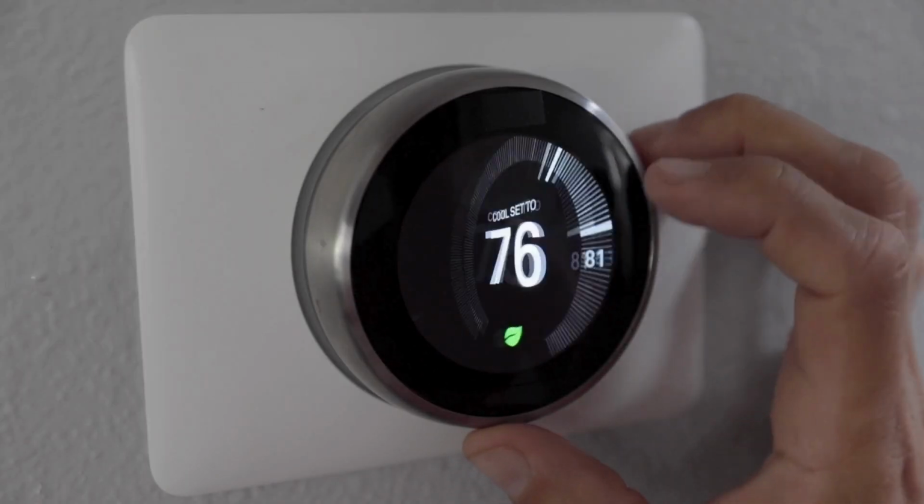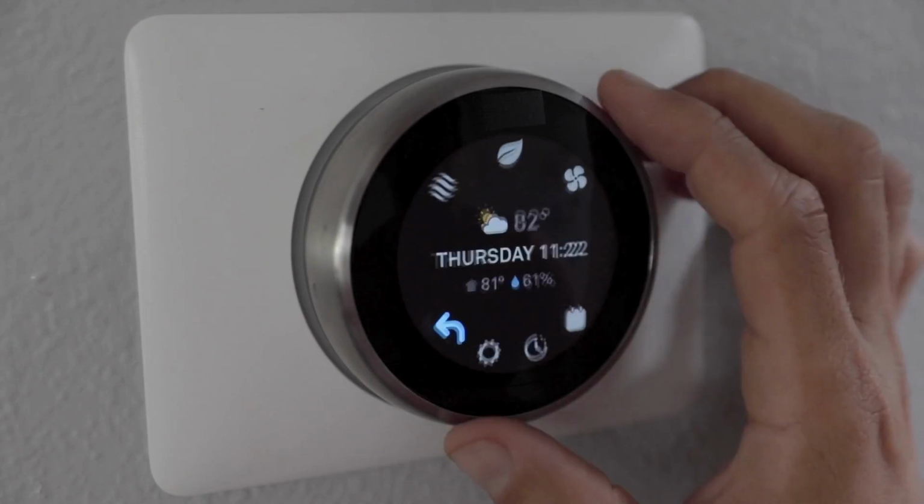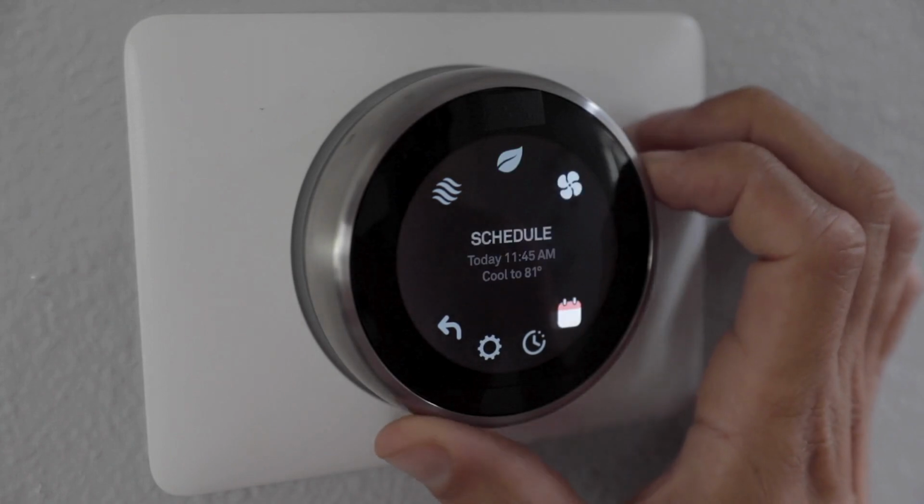The thermostat senses the room temperature, compares it to the set point entered by the occupant, and decides how the furnace and air conditioning system should respond. The comparison device can be complex in commercial HVAC control systems, involving multiple control inputs, computer logic, custom programming, and multiple control outputs. These systems are often referred to as direct digital control, or DDC.